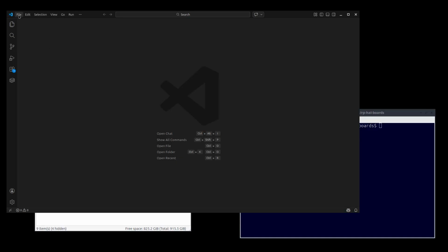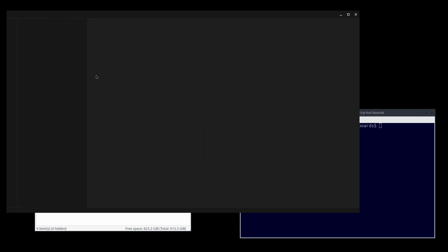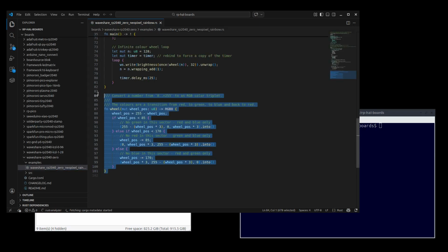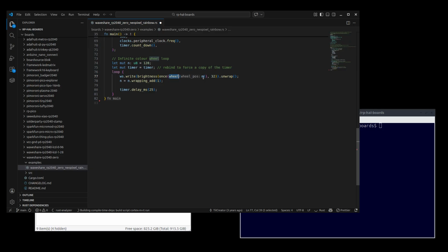You can open the project directory in a code editor like Visual Studio Code. After you make a change to the code files, you can build the project in the Docker container and flash the updated code to the RP2040-Zero. Do not forget to run the elf2uf2-rs command to convert the compiled binary to UF2 format before flashing. I am going to make a small change to the LED blinking pattern in the code and rebuild and flash the updated code to the RP2040-Zero.